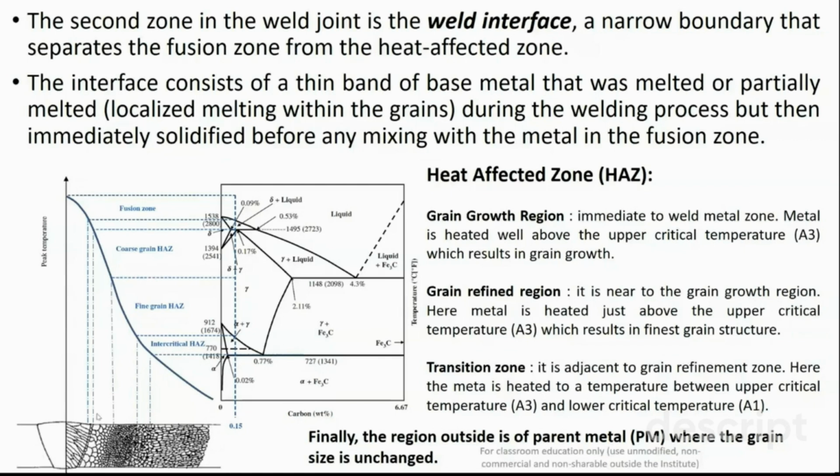In this region, close to this weld interface, the actual bonding takes place in the welding. Now you have deposited the weld metal and then solidification has started. So whatever heat is supplied in the middle section will migrate towards the base metal side. So this will be the direction of the conduction of your heat.